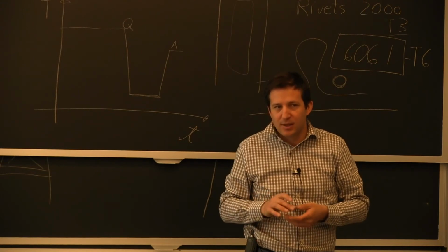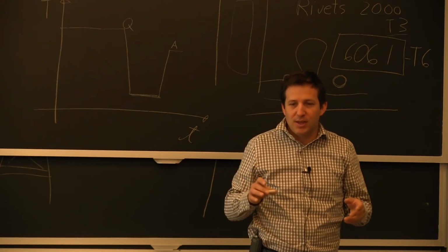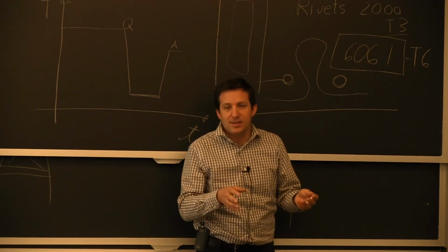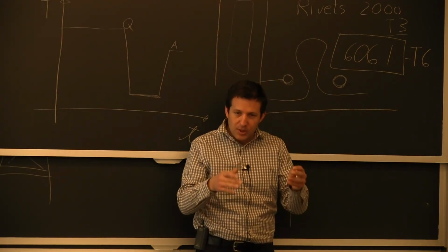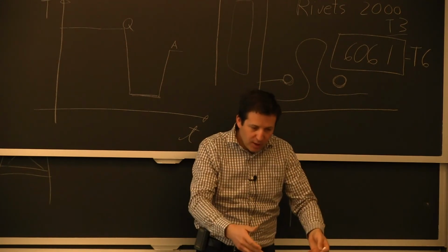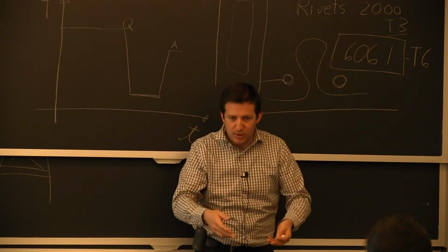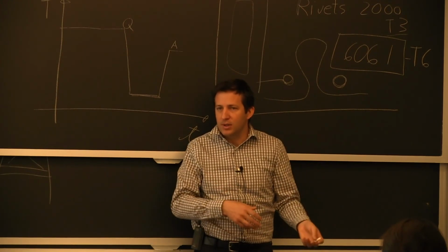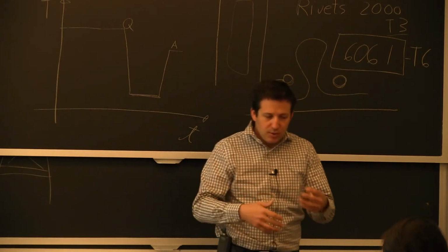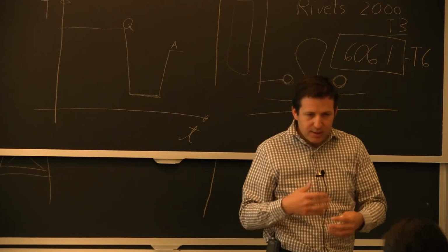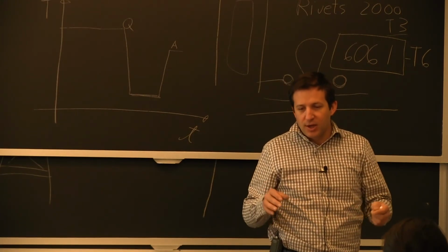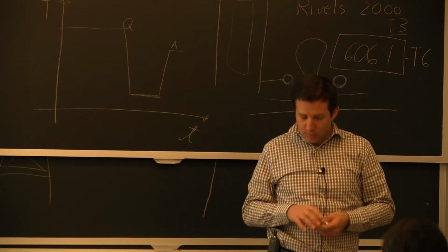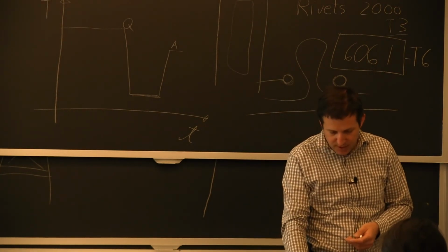The answer is yes. So to the extent that you're willing to go beyond a detailed analysis, which is only taking you so much, and ask, what if I have a variation in settlement? What if I have a high wind? What if there's more corrosion here than the average? If you're really willing to go through all that process, then your calculated factor of safety can use a lower value. The more you know, the less of a factor of safety you need.